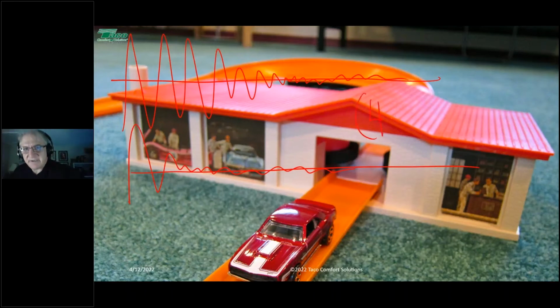4 gallons a minute divided by the CV of 10.3. Just for giggles and grins, let's call it 10, squared. All right, times 2.31, and that'll tell you the head loss at 4 gallons a minute through the Zone Sentry zone valve. So it's going to be 0.4 squared. 0.4 times 0.4 is 0.16. 0.16 squared is whatever it is, times 2.31. It's going to be maybe a foot of head, maybe if that.